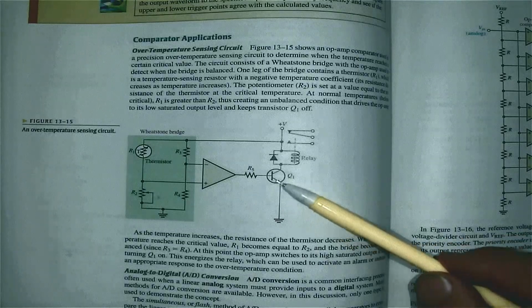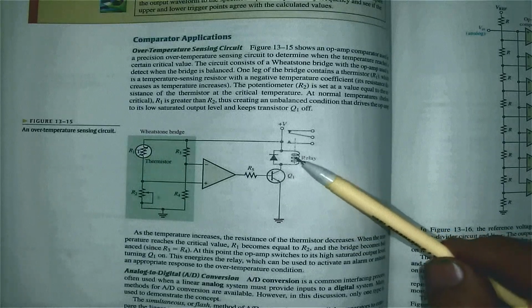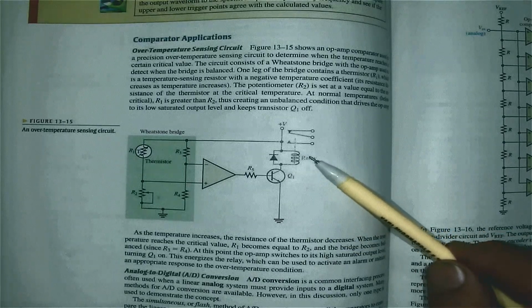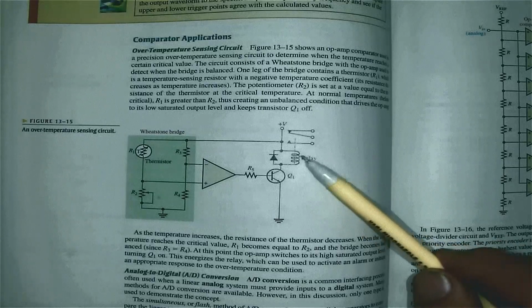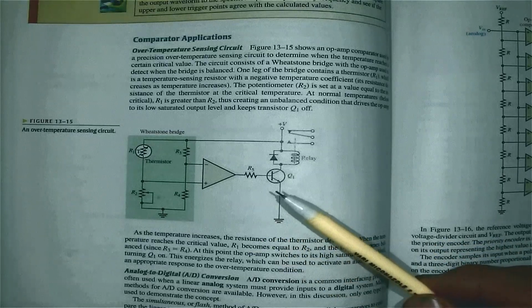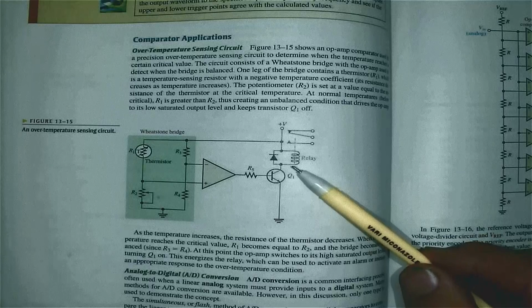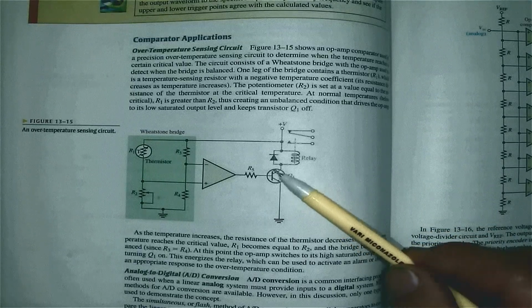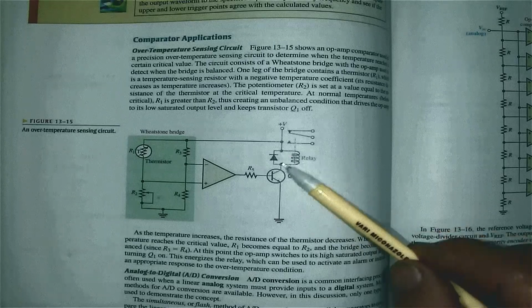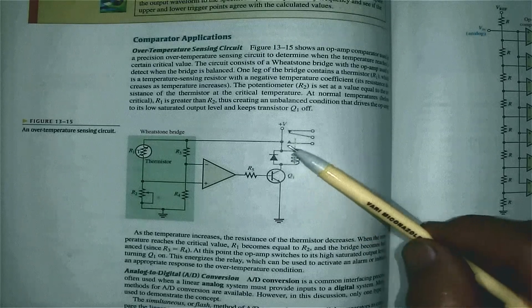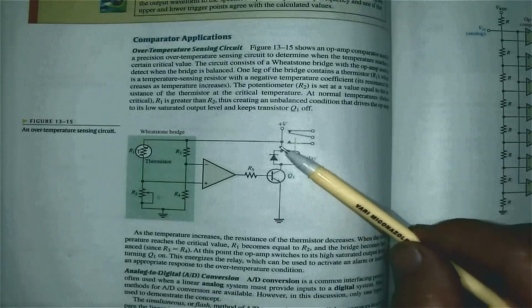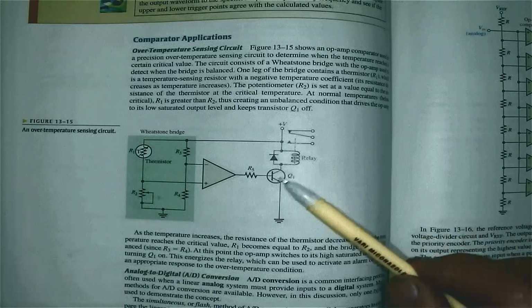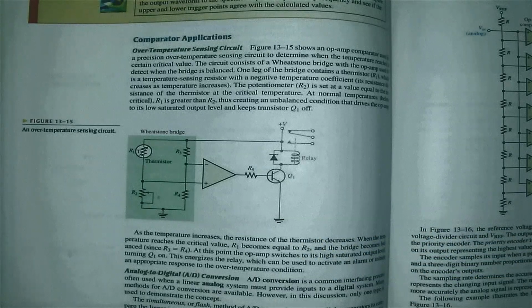But the moment this transistor turns off, the magnetic flux of this coil collapses and generates an EMF with the opposite polarity. That means the polarity will then be positive, negative, and that voltage can be fairly high, and it can damage my transistor. Now this is for protection. The current will now flow through the diode. The diode will short circuit that and will protect my transistor. That is the over temperature sensing circuit.